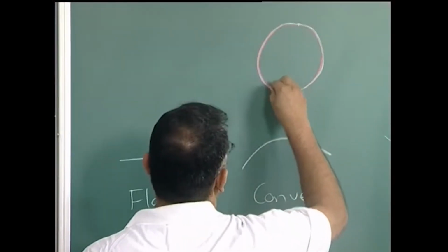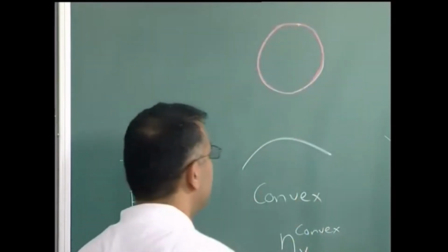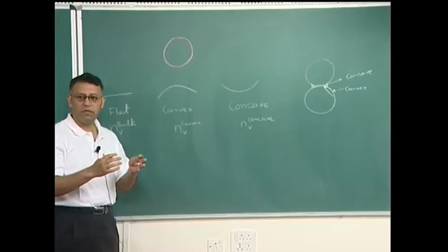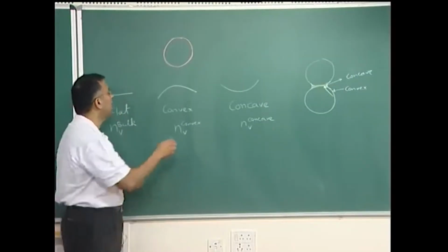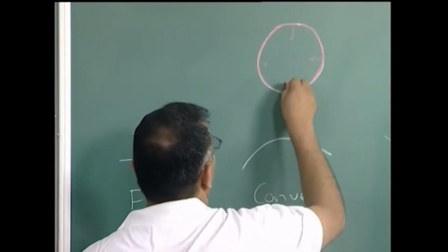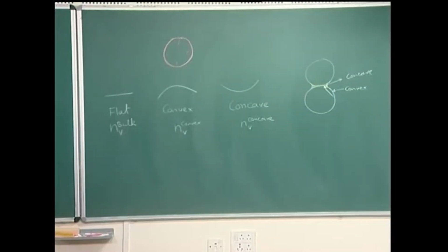Now, these atoms on the surface are in a state of higher energy, and therefore the surface would want to shrink itself, it wants to pull itself on itself. In the process it will tend to exert a pressure into the crystal, because the atoms on the surface want to get bonded more, they want to get closer to each other, and in the process they actually exert some sort of compression on the particle.